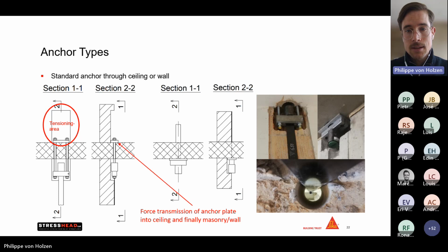As well, in those cases, the big advantage of the system, or of CFRP, is that it's so lightweight. Now, as you can see, of course, if we have to reinforce a building from the outside or a wall from the outside, we can just pass the tendon on the facade. Let's say we have to strengthen a stairway inside of the building. The only thing we have to do is make a local perforation.